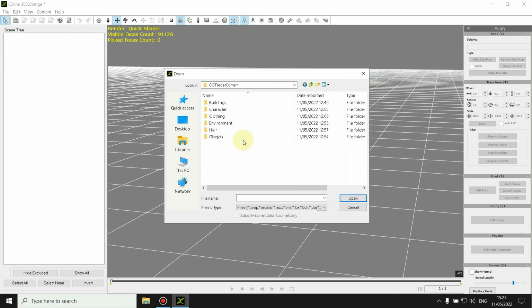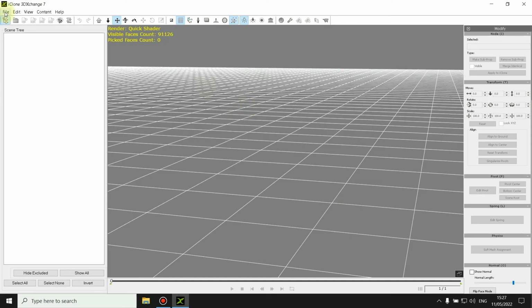So when you get something from Mixamo, it comes with character and animation. So you want to make sure that you basically put it in using this basically. So let me just go into here and you don't want to put in a pre-character in there. You want to make sure it's a blank template because the character is going to come with this anyway. If the character didn't come with the animation, by the way, if you found an animation off a software and it's just the animation, you want to make sure you put the character in here first by editing in 3DXchange and then put the animation on top of the character.